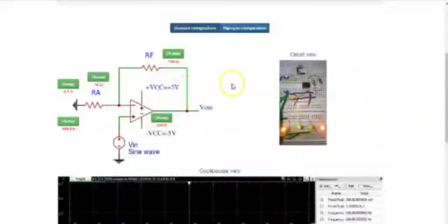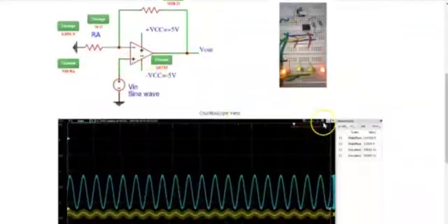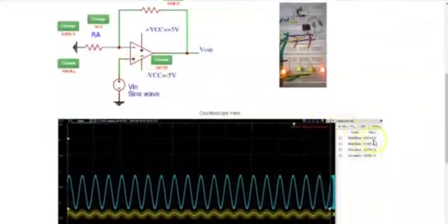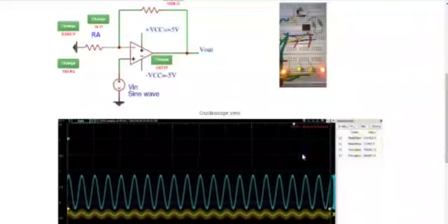In high-gain configurations, it is possible to analyze the performance of the amplifiers up to a gain of 101 V per volt. Let's start the analysis with Ra of 1 kΩ, Rf of 100 kΩ, voltage of 5 mV and frequency of 100 Hz with UA741 op-amp. With the input sine wave frequency as 100 Hz, observe the peak-to-peak amplitude of input and output are 11 mV and 1.10 V respectively, which demonstrate a voltage gain of close to 101.